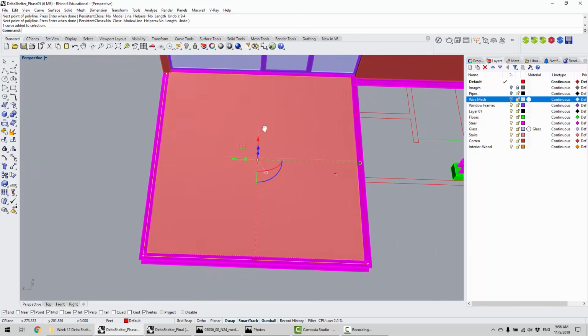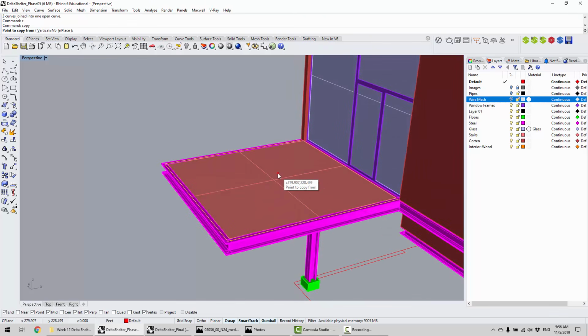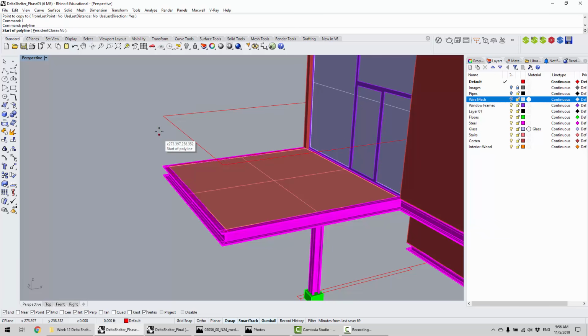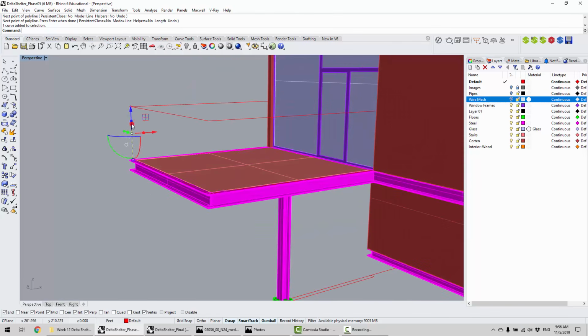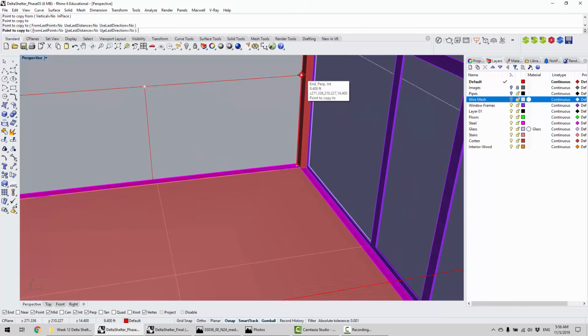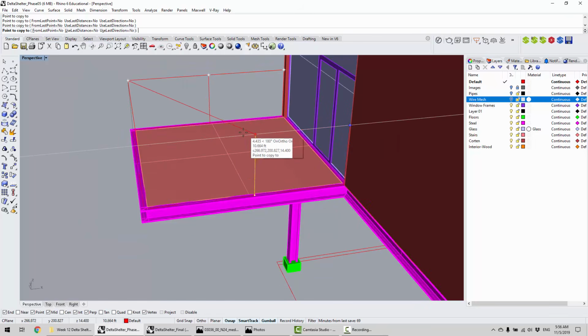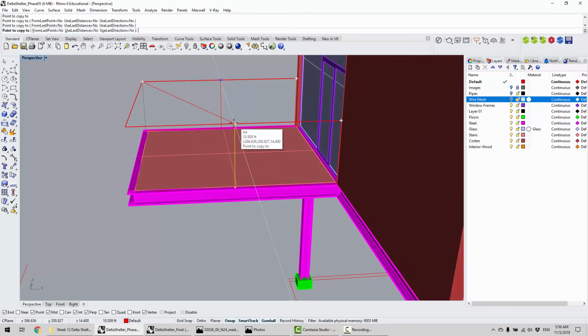And then you can complete the other edge. I think I already had a curve that was already there. So just join these, right? Copy vertical, click anywhere, pull it up just 3, right? So that's 3 feet in between them, okay? And then just draw one of the first vertical corners or posts, and copy this midpoint, endpoint, should be somewhere here. Okay, midpoint, right, corner.